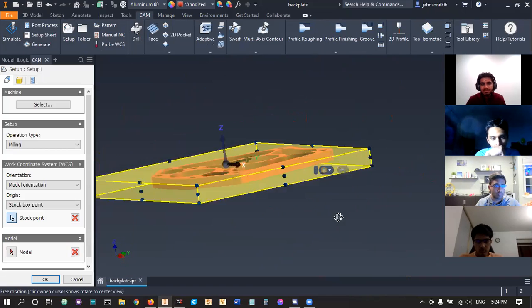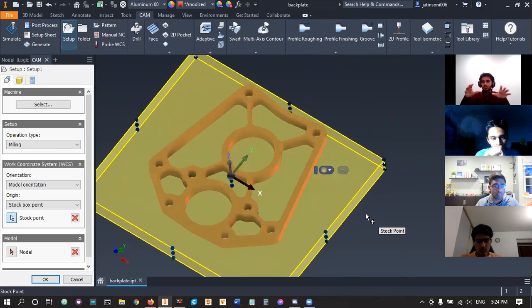This basically defines what your piece is, where does it start? First of all, the way CNC machines work is they don't know exactly where they are relative to the whole machine. The CNC doesn't know that it's in this corner of the machine. All the instructions in the G code say is that starting from this point, go 10 inches left, go 5 inches right, and cut out this piece. So any time we CAM, you have to define an origin point. That's where all my CAM will start. That's where everything will be referenced off of.